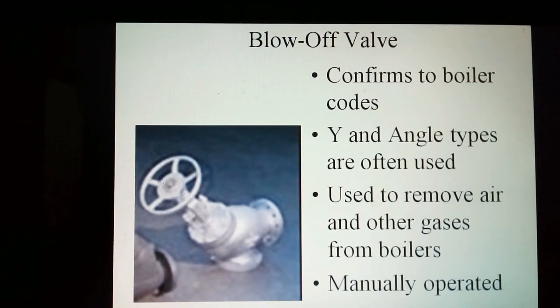Blow-off valve. It conforms to boiler codes. Y and angle types are often used. It is used to remove air and other gases from boilers. It is manually operated.